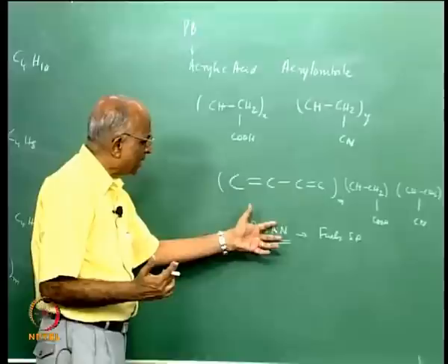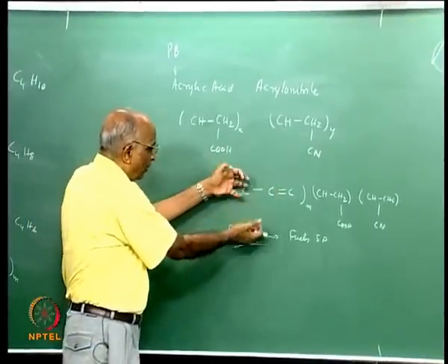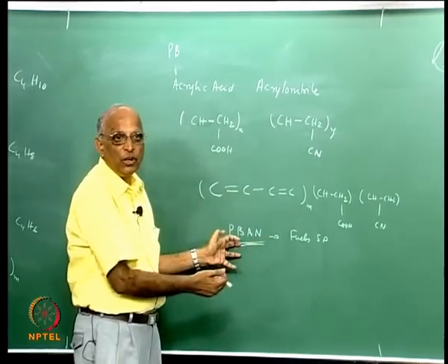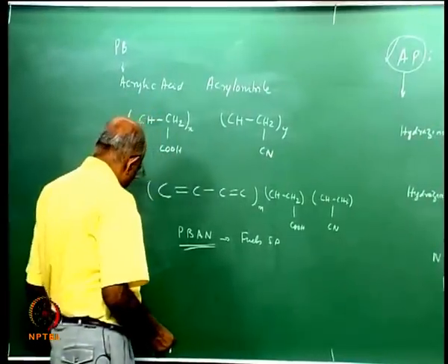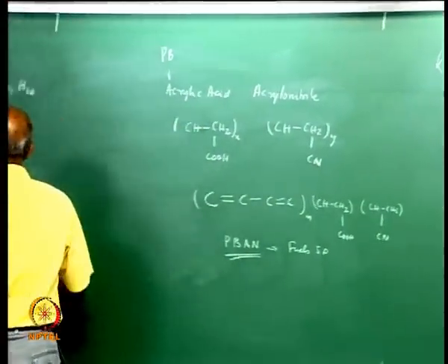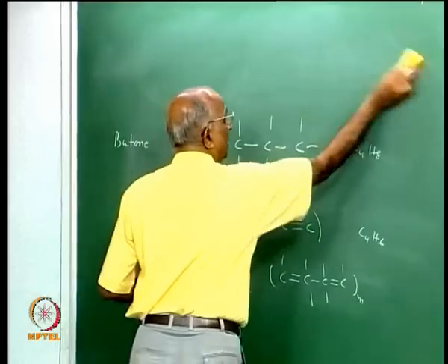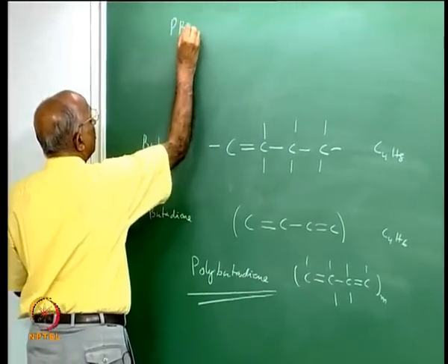It is possible to make it as a binder, and it is possible to have the rubber part of it have some more hardness and strength, and that is how you use the polybutadiene. Therefore, we say, well, the first fuel which I can think of using for a solid propellant is polybutadiene acrylic acid acrylonitrile, which I call PBAN.